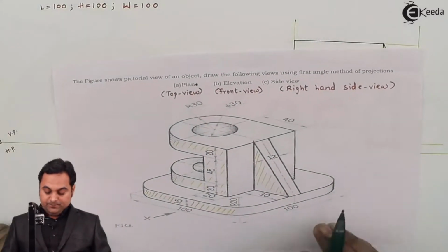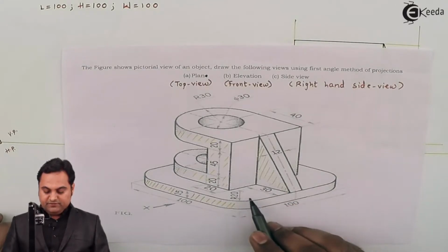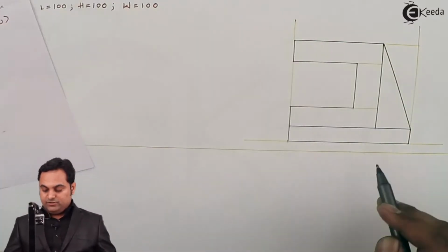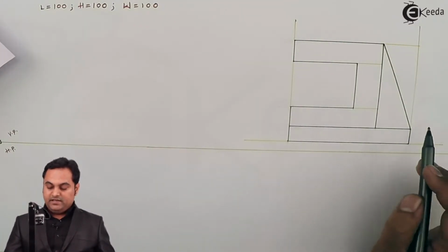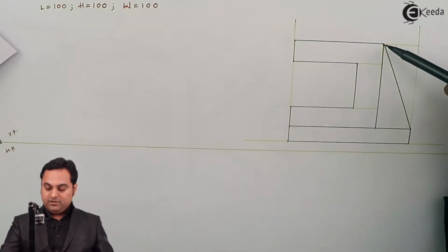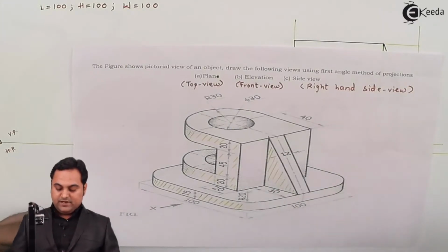Next, similarly, for this triangle, it is behind this plate which is of 15 mm height. So again, between both of them there should be a dark line. So here I have drawn a dark line, and even the triangle and these two plates are not on the same plane. So again there is a dark line as the plate is forward and the triangle is backward.